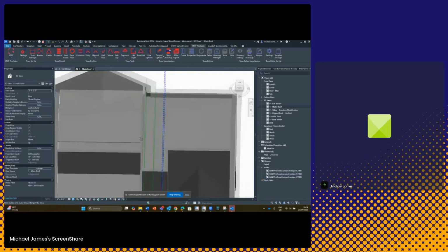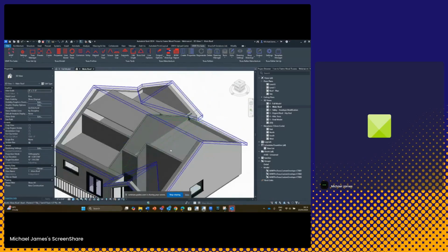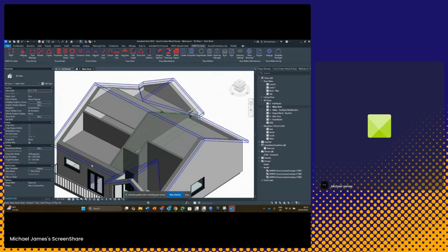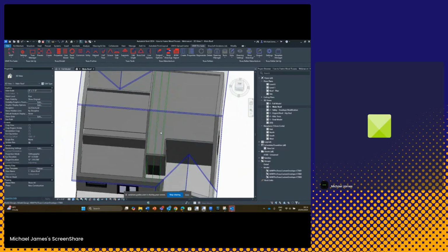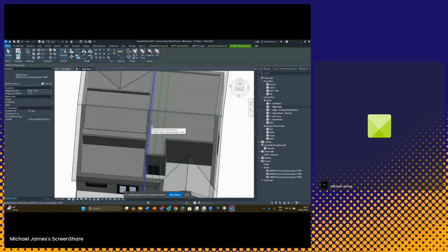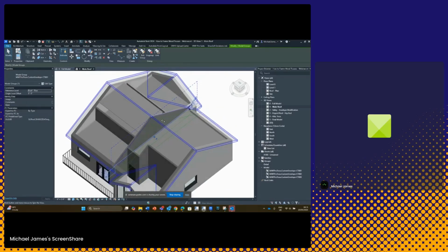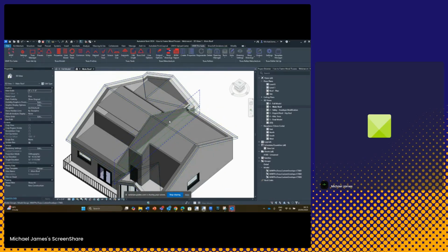Okay, this is exactly what I want, because if I generate trusses using these supporting elements on the left and right hand side, the profile or the envelope generated for the truss would then take on the shape of this part of the roof, which is not what I want. I want this to be a consistent triangular shape from start to finish. So what we can do is copy any of these model line groups, because once we generate these truss envelopes, they're created as model line groups.